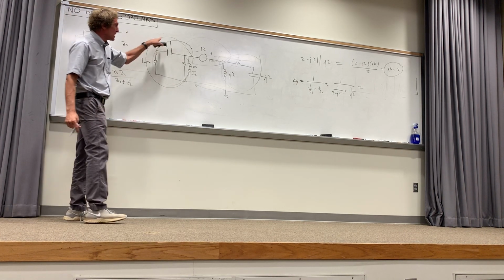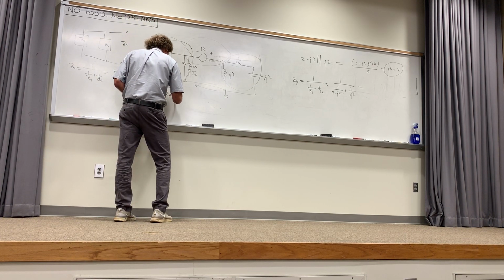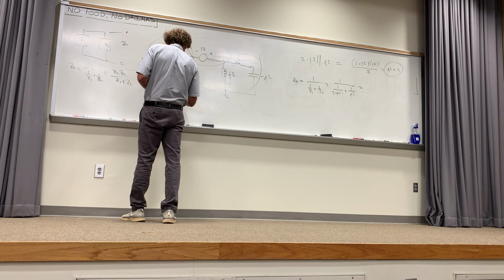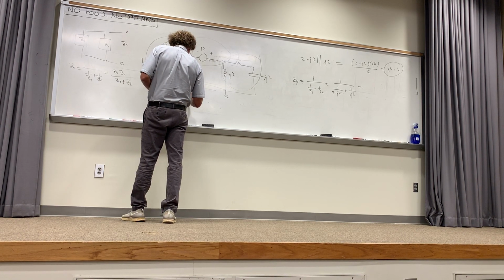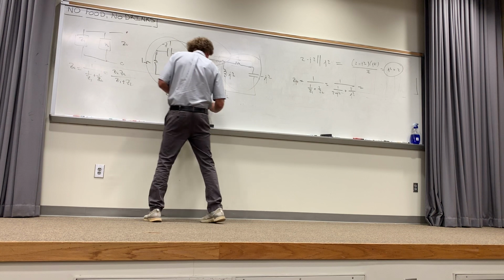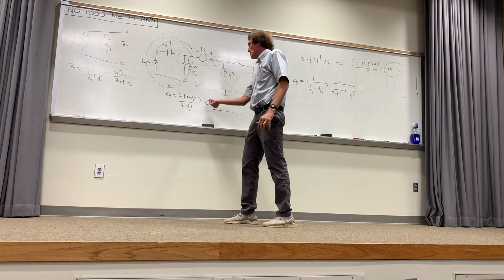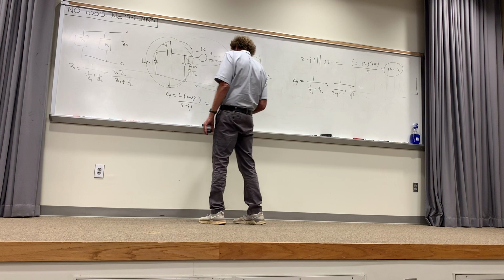So for this one right here, the second impedance, I can say that this Z parallel would be equal to 2 times 1 minus J2 over, then it's 2 plus this, so really 3 minus J1. I can use what's called a complex conjugate: take this thing, conjugate it and multiply top and bottom by that to get a single value.